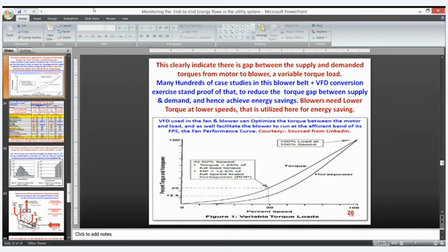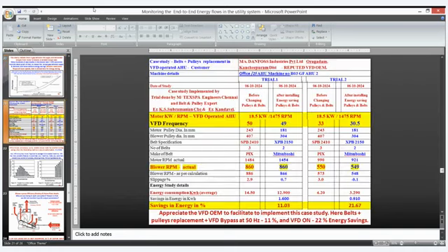It is a very low cost investment. Say it's costing around 10,000 or 20,000 for an existing VFD operated blower. This gives a savings of almost 15 to 20%. I can also show you a case study done in Danfoss, a reputed VFD OEM, at the Chennai plant. You can see a 18.5 kilowatt, 25 HP blower, an AHU blower.